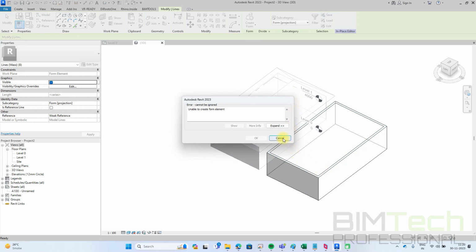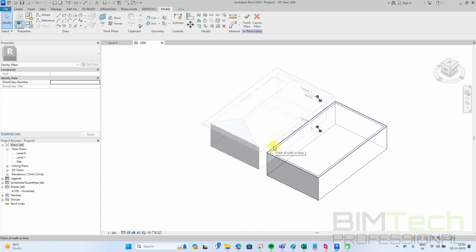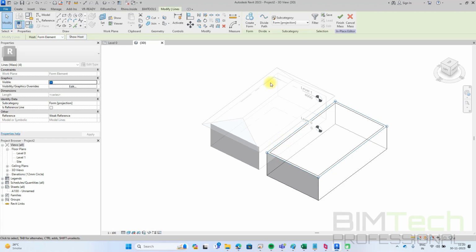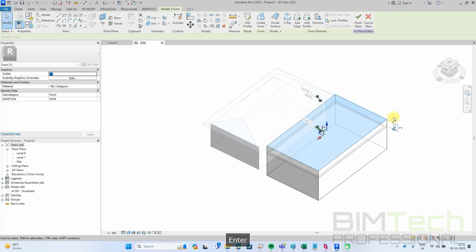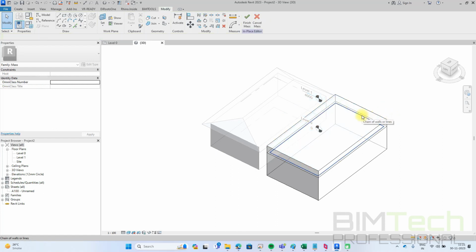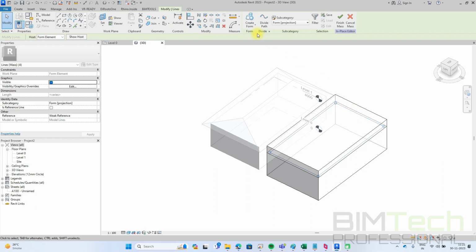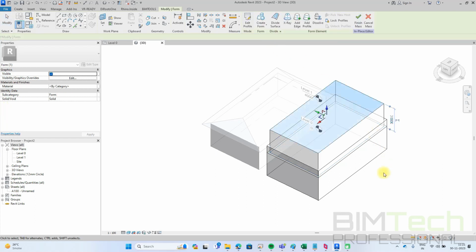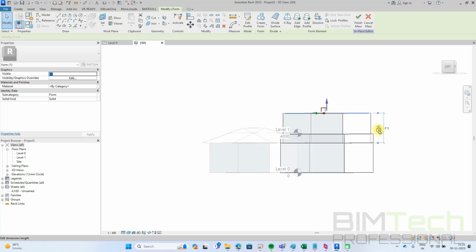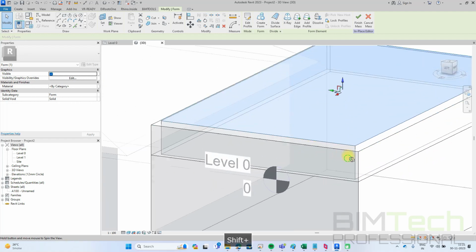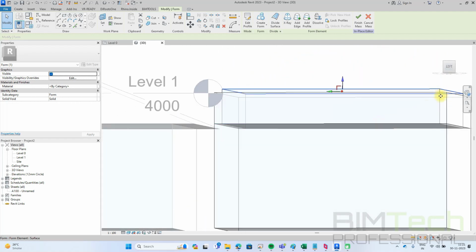So the better way to do so is, first of all, let's create a form with the outer boundary. So we'll click on the outer boundary, Create Form, set the height of the parapet to 900, okay, and then we click the inner boundary, click on Create Form again. We want the inner form to surpass the top of the outer form, so we'll set the height to 1000 so that it is greater than 900. Now, see, it is coming out of the outer boundary, right?